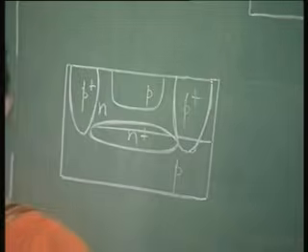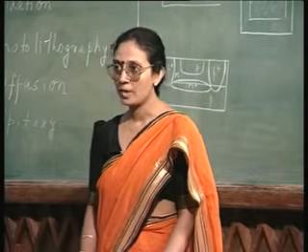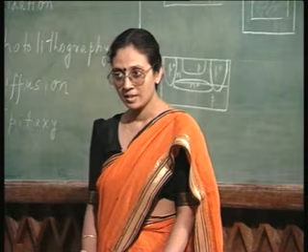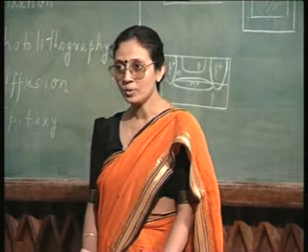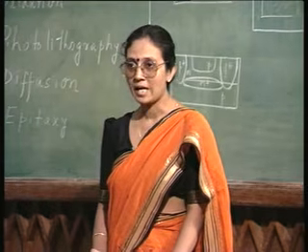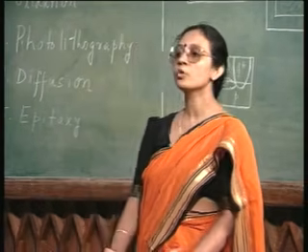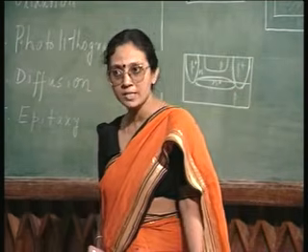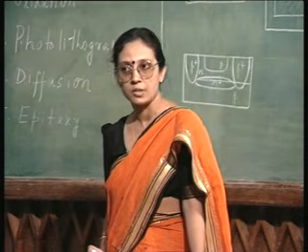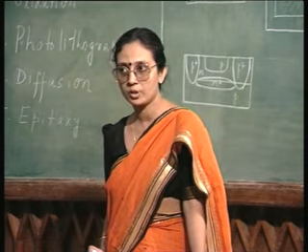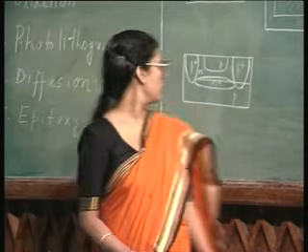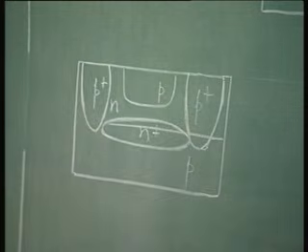Again I am drawing it very simply, but you know, in order to realize a P region, again I have to have oxidation, photolithography and diffusion. Therefore, almost in every stage of processing these three steps have to be repeated: oxidation, photolithography and diffusion. Okay? So, you have realized your base region.